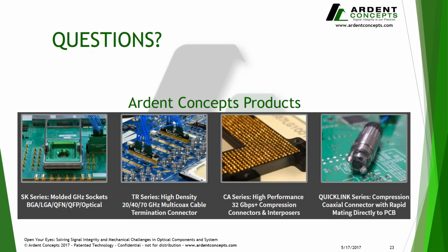After the webinar, I do think we make these slides available to our attendees, so we can look back at that as reference of what we're talking about here. So one of the things is we did use some more advanced materials. There was concern that this was a medium volume production environment, so we had to make sure that the guiding of the leads didn't cause any wear of those guide channels, which could have put foreign object debris into the measurement system and reduced signal integrity over time. So we did look at some really advanced engineering plastics to make sure that wear wasn't an issue.